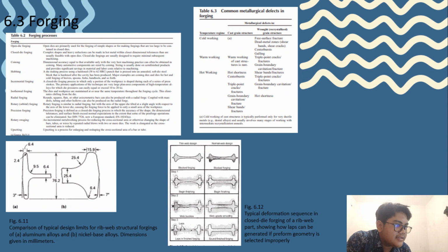However, a shape change across the width and or along the circumference of the roll makes the process especially attractive for certain applications. Roll forging essentially combines the advantages of rolling and incremental forging in one, as you can see in figure 6.11.